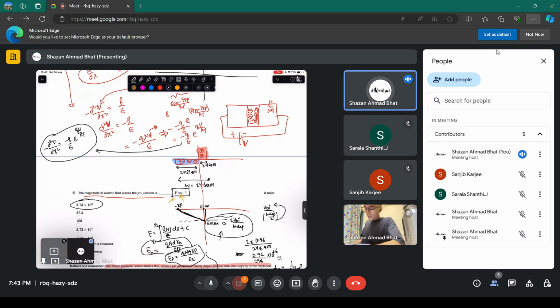And this particular equation is solved numerically in all of the device models. You might hear people use this in research in order to model the device, because there is a potential on this side and a potential on that side. You can solve it numerically. You guess some potential, you obtain another potential, and it keeps on going in a loop. You write a program on a computer for solving this differential equation, and it gives you the variation of the potential. Technically, it gives you the band diagram by solving this equation.